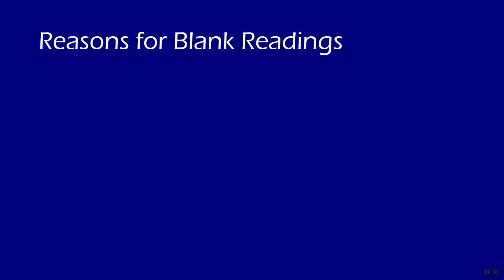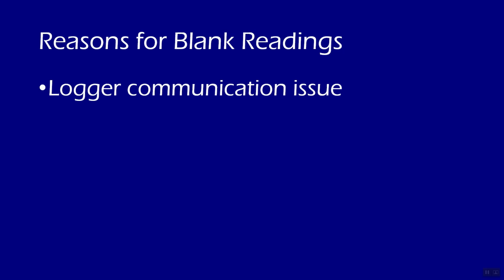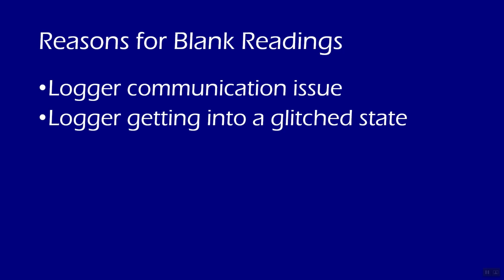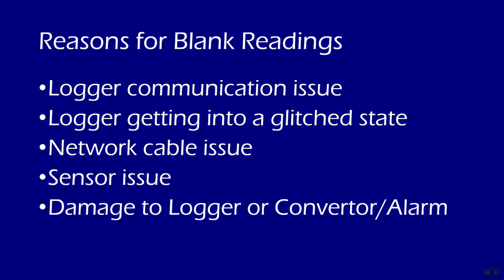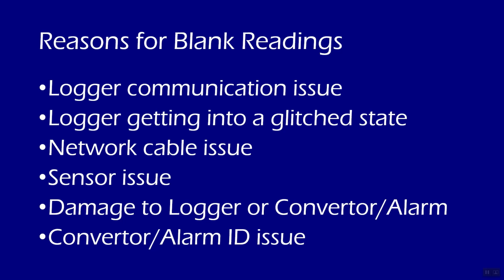It could be a logger communication issue, it could be the logger getting into a glitch state, a network cable issue, a sensor issue, could be damage to the logger or the converter, or it could be a problem with the Convertor ID. So let's go through each of these points.